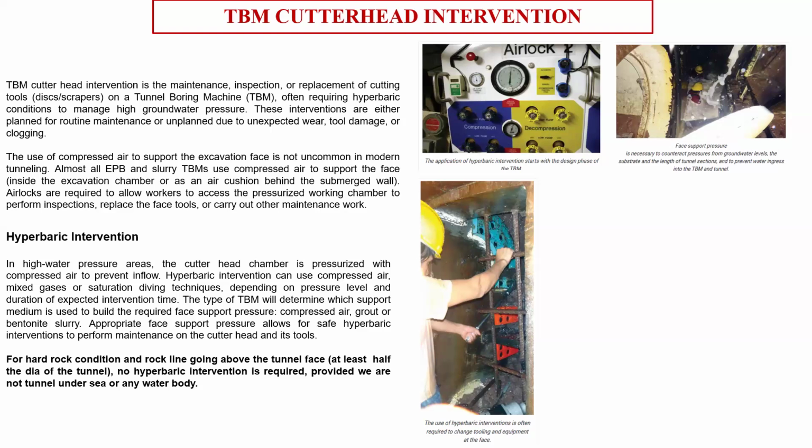When you cross that 500-meter region, after that we got a 200, 300-meter stretch where we had open ground or a park, a very huge park or very open land. There we applied a high face pressure and made the TBM progress faster. In the initial 500-meter stretch, we applied a face pressure of 50 kPa, 60 kPa, so 0.5 bar, 0.6 bar.